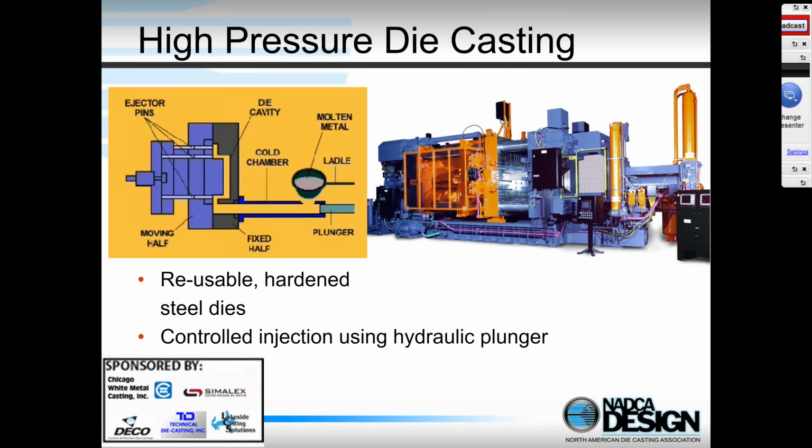So as we just talked about, when we talk about die casting, we're talking about castings produced in a die casting machine, and it's a large, complicated, hydraulically and electrically controlled machine. I'm showing a picture of a machine on the right. And so generally, we use this high pressure to force the liquid metal at high speeds, at high pressures, into reusable steel molds. And so the picture on the right is a Buehler-Prince die casting machine.